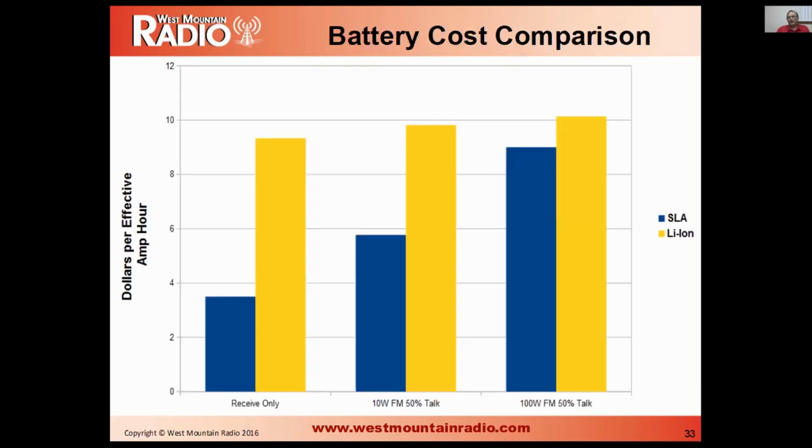So the moral of that story is don't use a lead acid battery charger on a lithium ion battery, unless there's electronics in the battery that are designed to get around that.